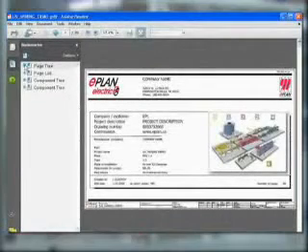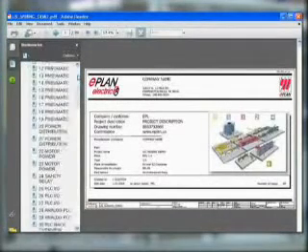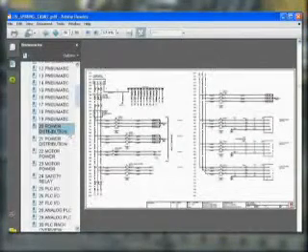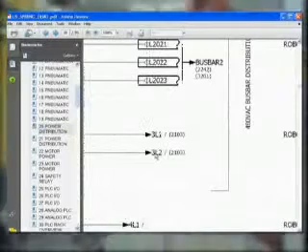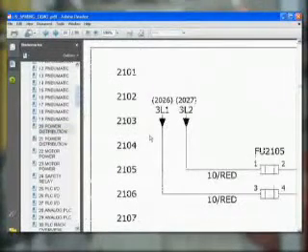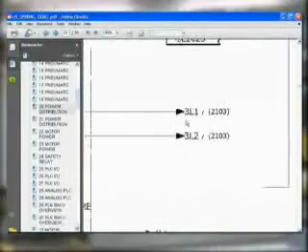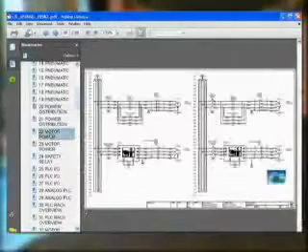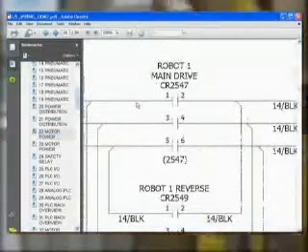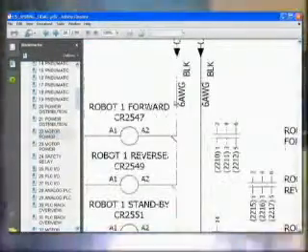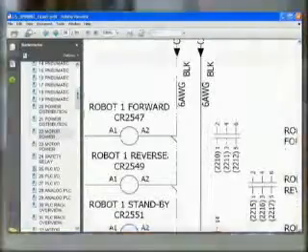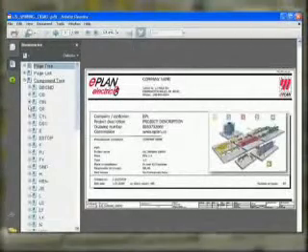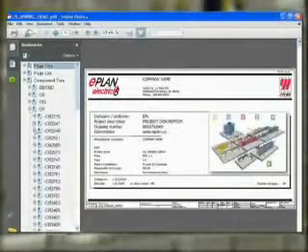This intelligent PDF can be opened in any viewer. The page tree is still available. The Eplan connections are maintained through hyperlinks. You can jump between pages with the interruption points. The contacts can also jump to the coil. The component tree bookmarks give quick access to all the components.